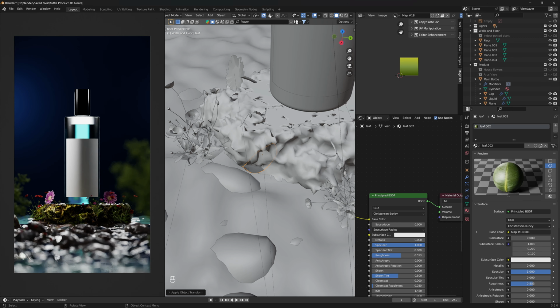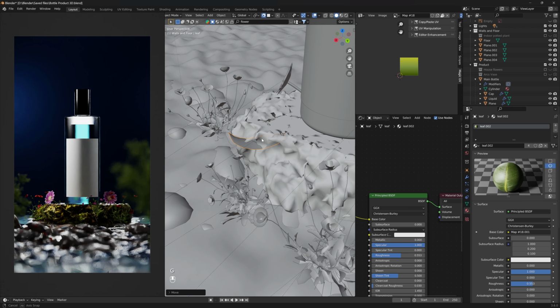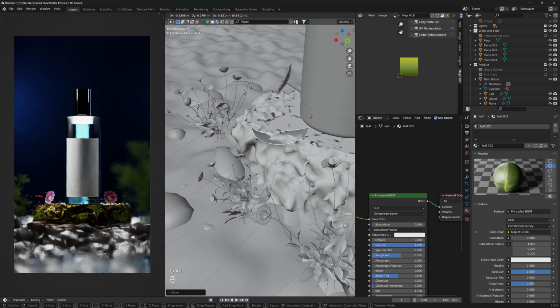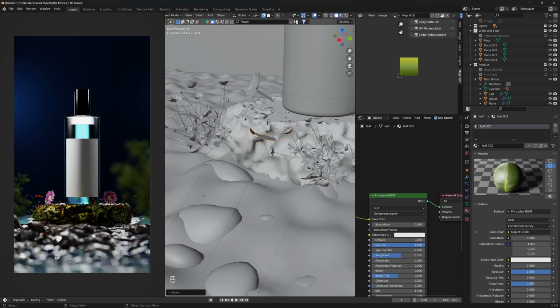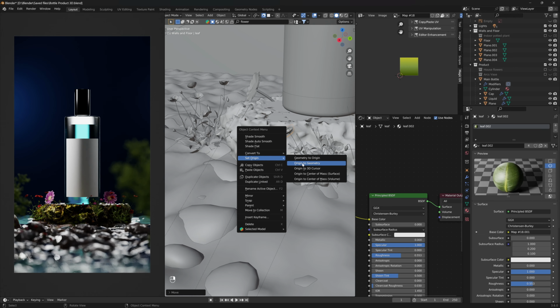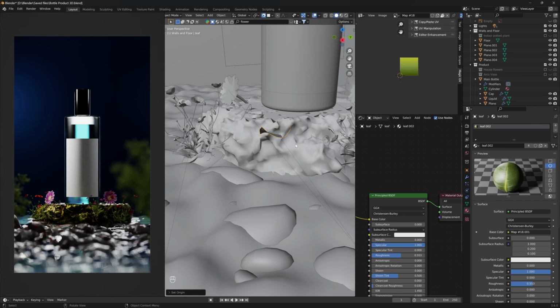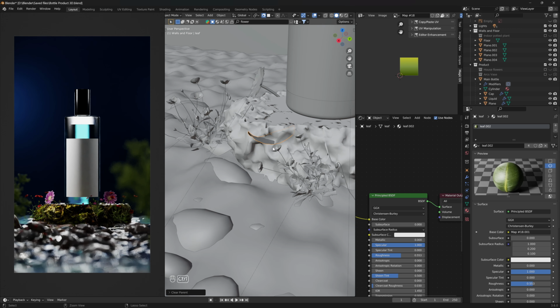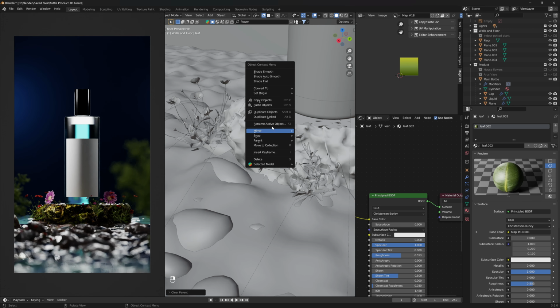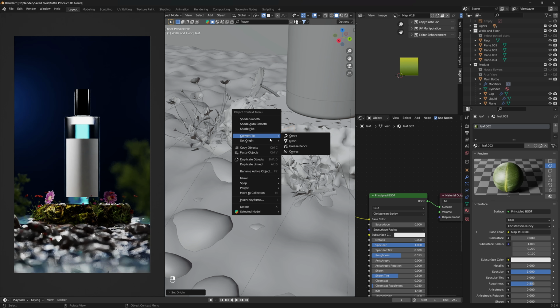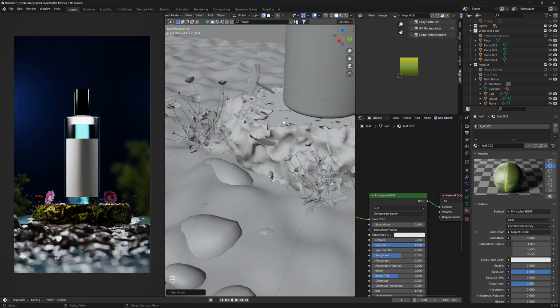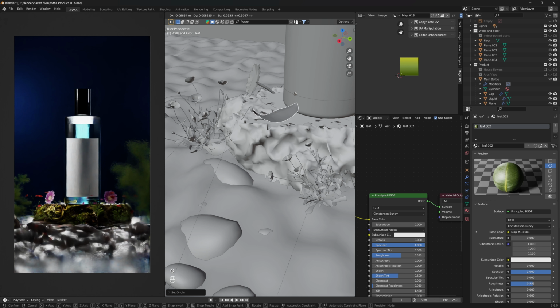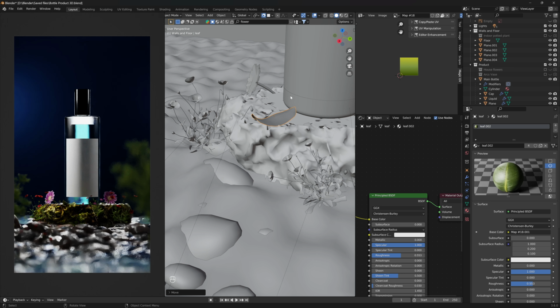and let's turn on snapping and face project, and then G. Wait, what? It should snap on this. Actually, I think it is snapping, but because of its geometry, right click, set origin to geometry, right click, parent, clear parent, and keep transformation. Right click, set origin to geometry, and G, now put it over here. I don't know why it's not working. It should work, by the way.